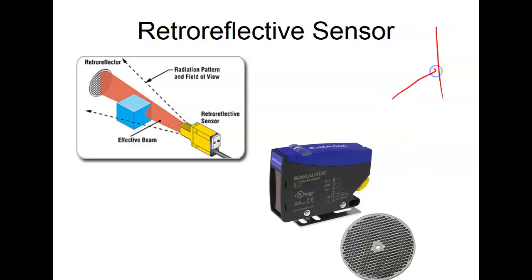If light came in like that, it would bounce off like that. But what a retroreflector does is it comes in and goes back out toward the source. On a stop sign, you can actually see when you exceed the viewable angle, because you'll see it real bright up here that says stop, but the closer you get to it, it dims out, right? People wear these retroreflective vests all the time when they're riding bicycles or out working. So retroreflectors are reflectors that work within a viewable angle. It's not an infinite angle.